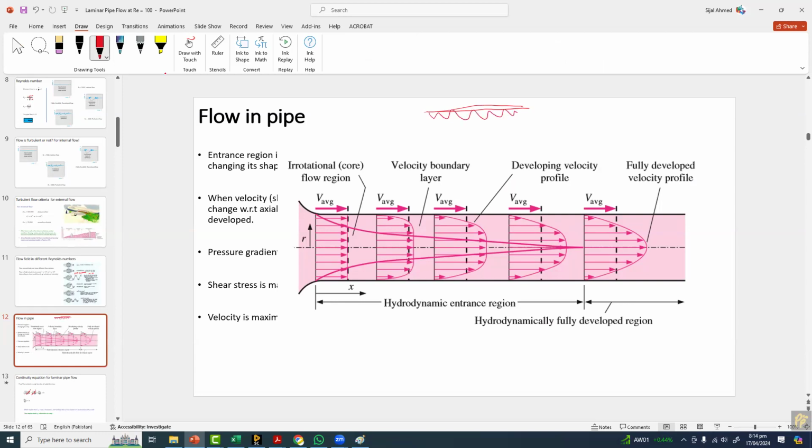Okay. So any particle which will be in contact with this region on the pipe. If you take a look with your bare eyes, you will see that it's very smooth. But if you go to the microscopic level, there will be some roughness on your geometry. This is the roughness height. You might have heard about this thing, epsilon. So there's some roughness in the pipe over there. Okay. So any particle which is trapped here will stick to the wall of the cylinder, and the velocity will suddenly become zero.